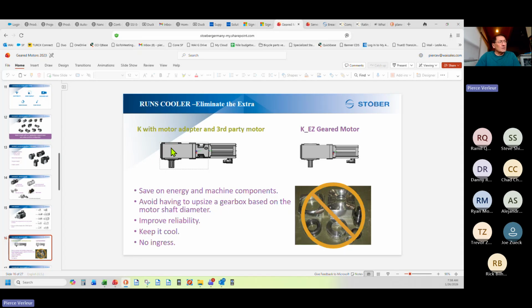The gearbox, again, within its operating temperature range, with proper lubrication, properly maintained, I'm going to say 3 to 4 years under continuous operation. Not so much the motor, but the gearbox is going to vary dramatically based on how much peak torque is going to be applied in its application. So this is a very subjective discussion. But nevertheless, that's about what I should see.